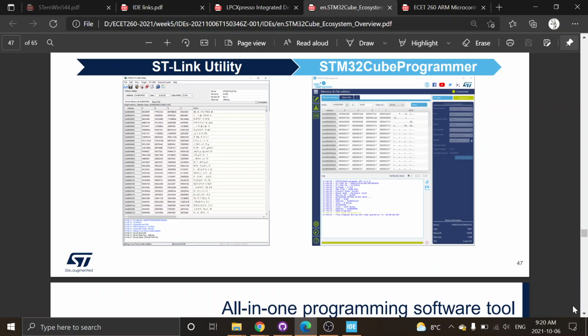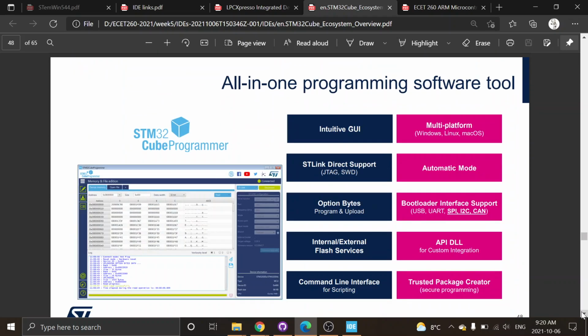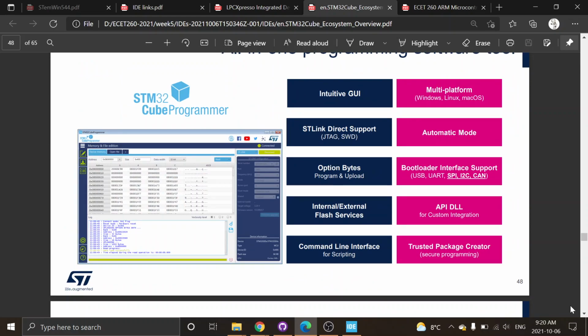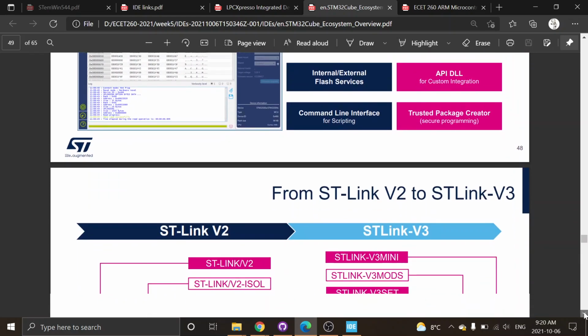You will find, for instance, TouchGFX is going to use that programming interface to actually program. So if you go and try and do it, it'll give you some weird error message, and it's just that it needs the STM32CubeProgrammer installed to have the tools to do all of its scripting and things. So, okay, we'll continue on with more of this.